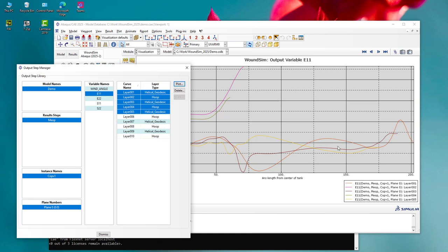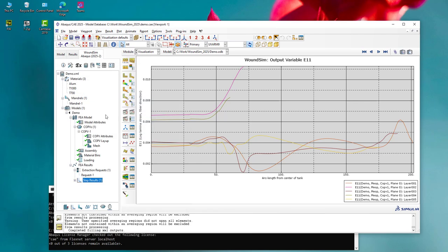So we've got easy access to all the stresses and strains along the base of each layer. This is a very handy results manager, because let's say we have multiple steps and we want to look at the stresses, let's say before and after autofrettage, the strains and so on, and different MEOPs. We can very easily select different steps but the same output request and compare. So I'll do that in a different way.